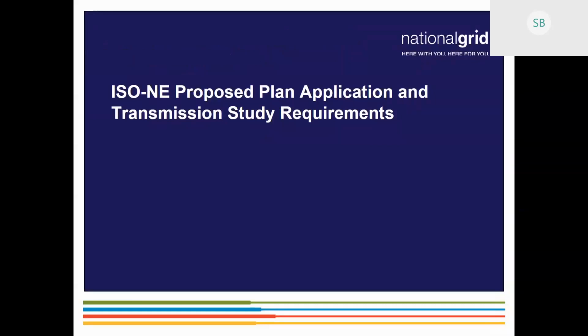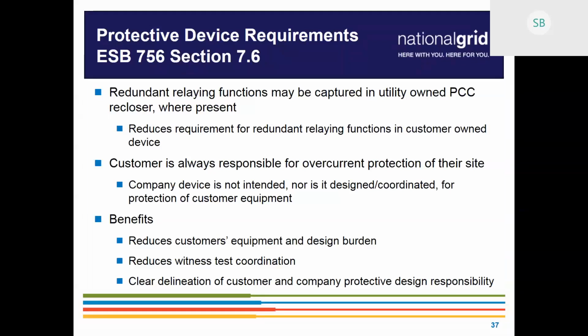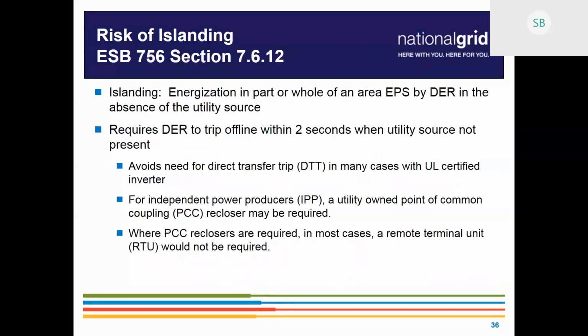Just a quick question. I didn't catch the last part on the risk of islanding, where the PCC reclosers are required in most cases, and whether an RTU is or is not required, from the previous slide? Yeah, so where we have the PCC recloser, we would not require a remote terminal unit because we have remote sensing and control of that recloser itself. So we would not need sensing and control of your